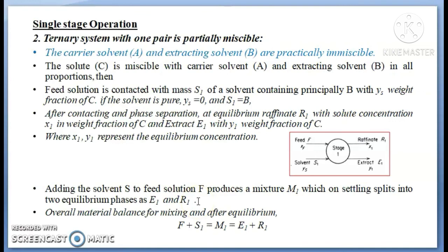So first of all, the feed solution is mixed with the extracting solvent S to form a mixture indicated by M1, which is further separated to give the two different phases at equilibrium, E1 and R1.